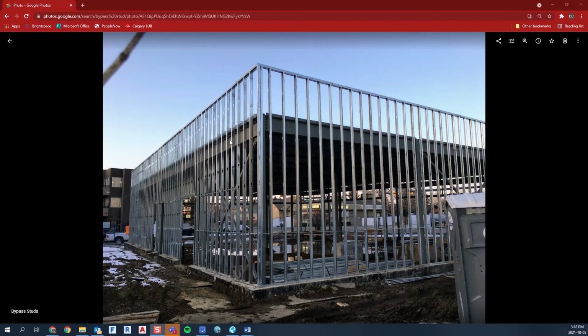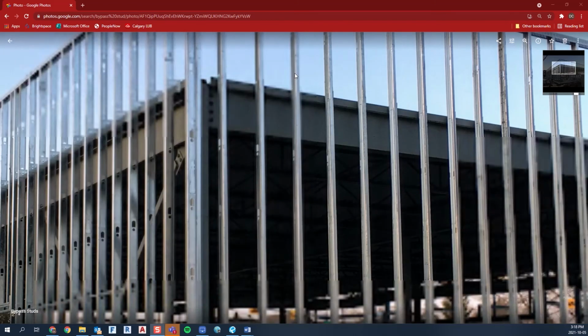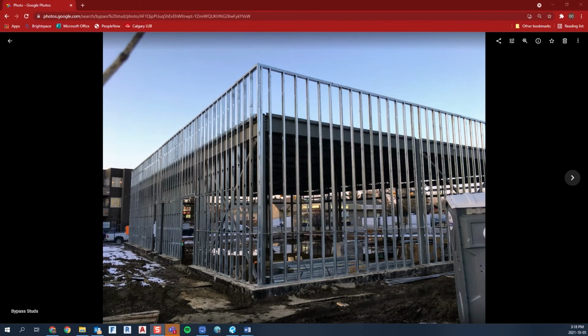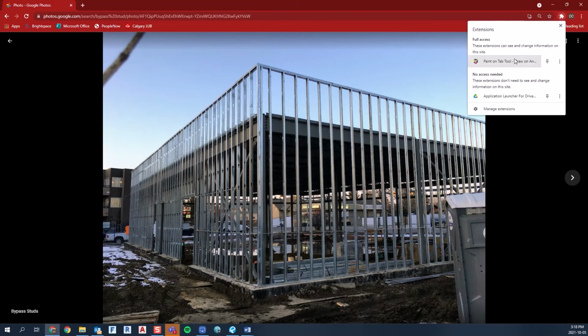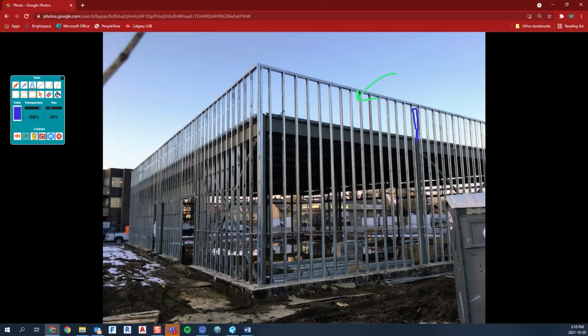And so just looking at a picture here of a bypass stud system, you'll see the difference there. The studs are clearly placed outside the structure. So the column's in behind there, and the studs are spanning past that. One of the benefits of this, right off the bat, that I could talk about is the parapet height. So quite often you'll see in buildings like this that this column extends up right there, and this corner column would extend up right here.